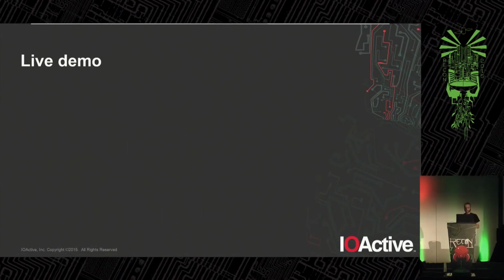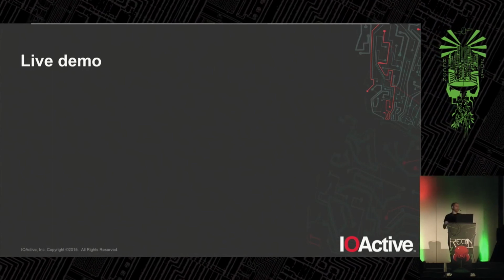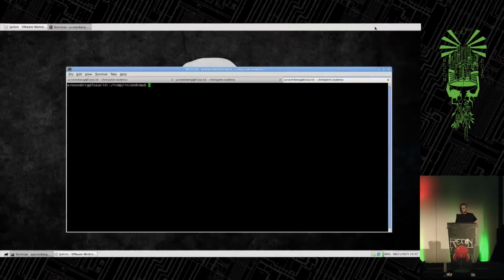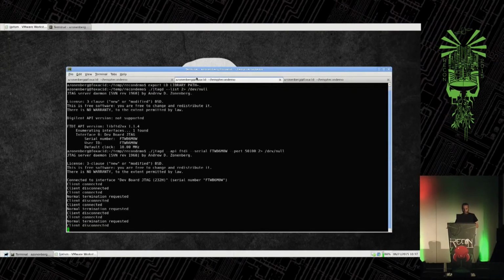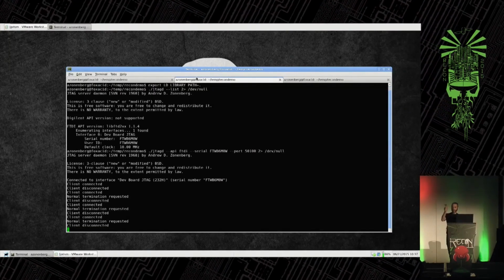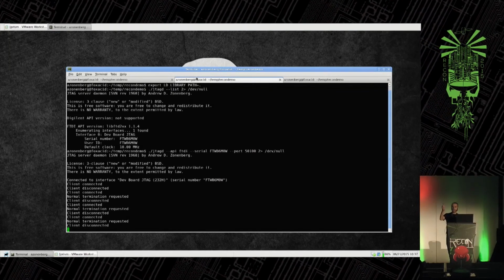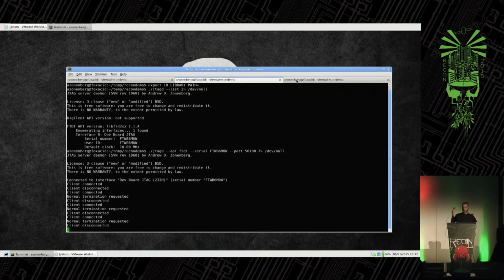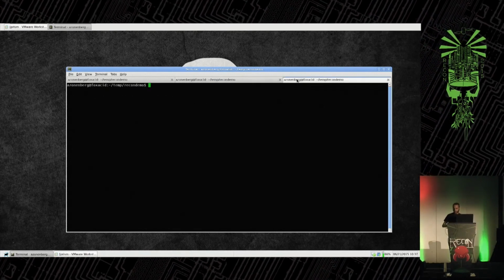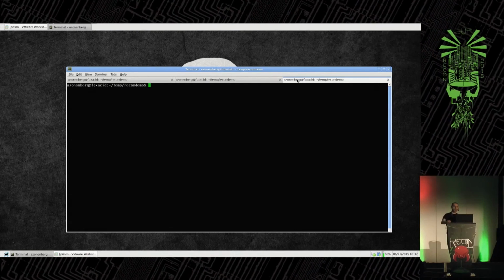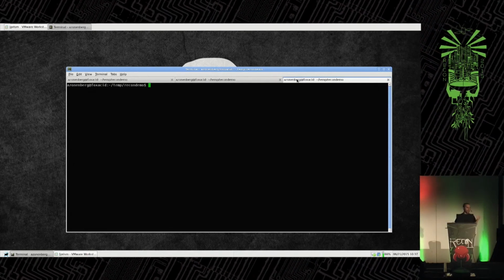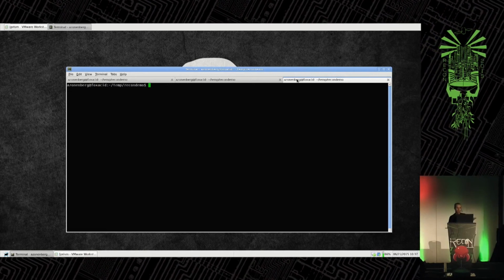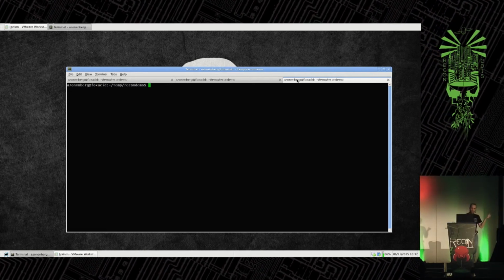Something like that. So now, time to tempt the demo gods. I have my JTAG daemon connected already. This is my dev board. It has a small FTDI 232 on there that I'm using for JTAG. And so what I'm going to do is create a bitstream using Libcrowbar that will act as a NOT gate and a buffer. And then I'm going to bit bang inputs going into there with the FTDI chip. And we should see one LED and then the other alternately lighting up.